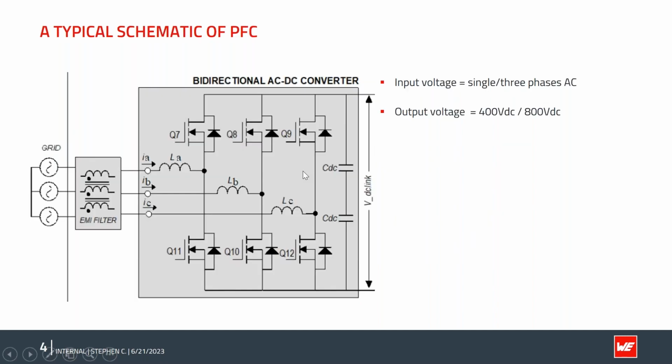Sorry, I missed something on the last slide. As you can see, the output voltage is 800 volt DC. So it is very important that we select components, when we design a three-phase PFC circuit, that can operate long term under the output voltage of 800 volt DC.